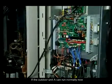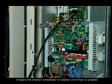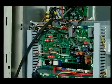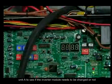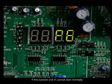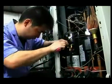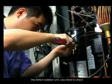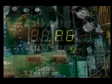If outdoor Unit A can run normally now, it means the inverter compressor of outdoor Unit A has no problem, but the electronic control probably has a malfunction. Now, you need to check the electronic control of outdoor Unit A to see if the inverter module needs to be changed or not. If outdoor Unit A cannot start normally, that means the compressor has a malfunction and needs to be changed. If there is no other outdoor unit of the same series near the defective outdoor unit, you need to check and repair as follows before changing the compressor.